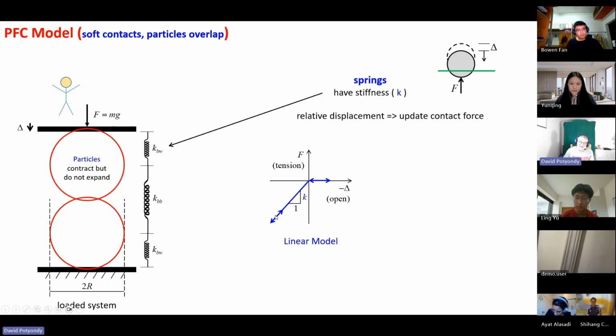So as we force it to overlap, the force gets bigger and bigger with a slope of K. And it'll go on forever. That's why there's 2 things here. It'll keep going this way. If I start moving it apart, it'll trace this curve back and forth. But if I start to form a gap, there's no stickiness, there's no force, there's no tensile force. It won't allow that, right? So this would be like a dry sand.